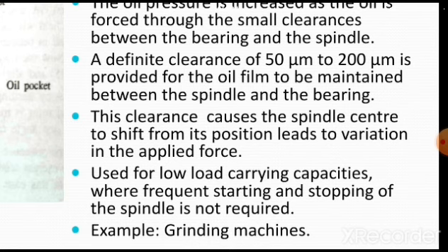So it is very clear: hydrodynamic bearings are used for low loads, not for heavy forces or heavy machining operations. So these can be preferred for light machining operations, on CNC machines where the machining forces are less and where frequent starting and stopping is not there. In those conditions, hydrodynamic bearings are more applicable.